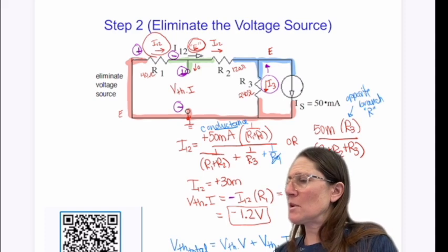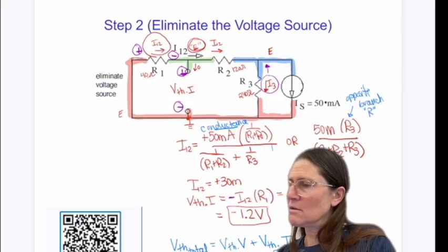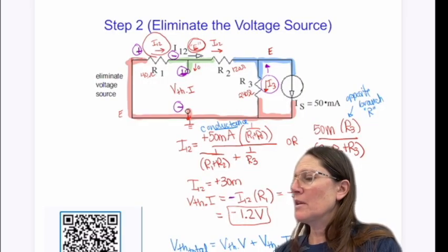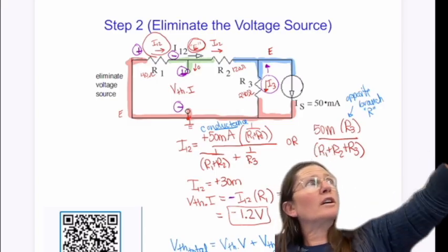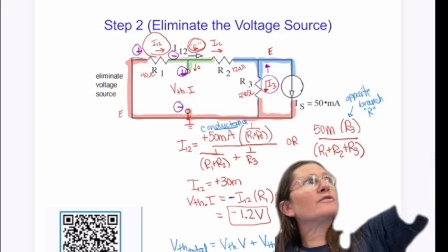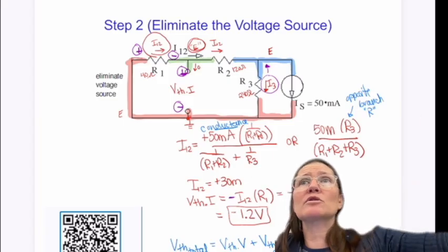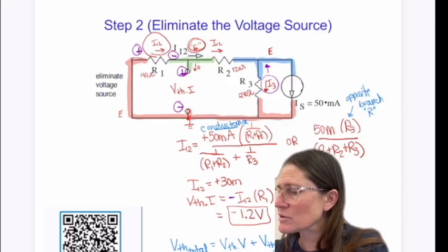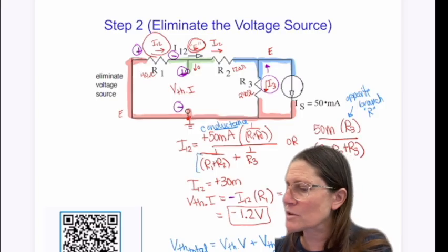All right, other questions? Yes. For I12, when we're doing conductance, why do you do 1 over R1 plus R2? Why is it not 1 over R1 plus 1 over? So kind of that same thought, you have just 2 branches, so the branch resistance is what you're doing the summations over. So this is the branch resistors. So summing up the branch resistors.